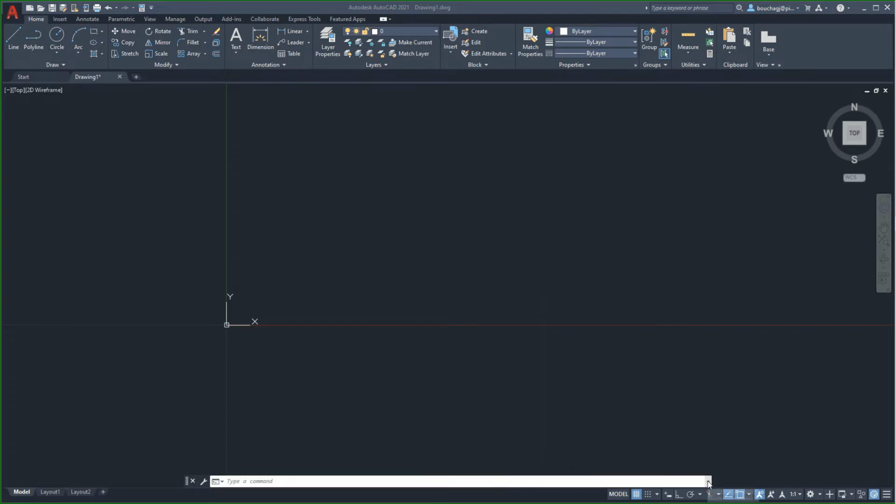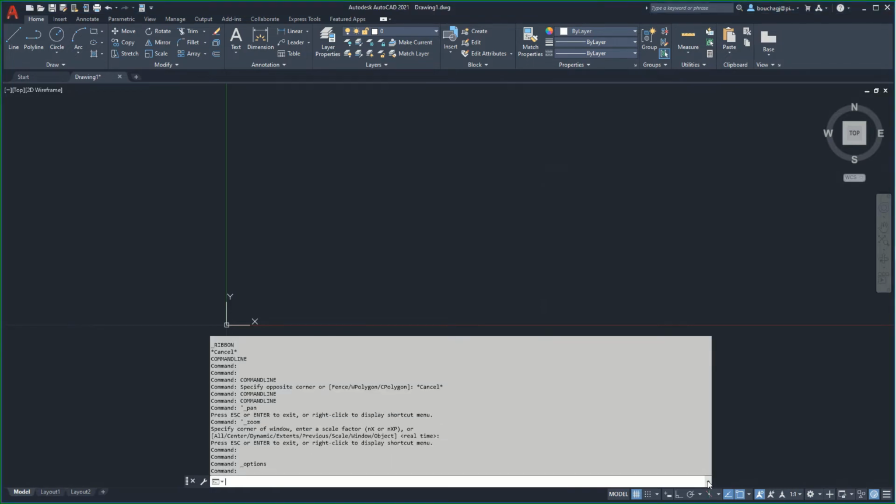At the far right end of the command line is a contextual menu arrow. Selecting this arrow allows for the command line to expand and reveal the history of commands and data input of the current drawing session. This history is extremely helpful in that we sometimes execute a command, but what we see on our display is not what we were expecting. Most often, this is user error, such as typing in an incorrect numerical value.